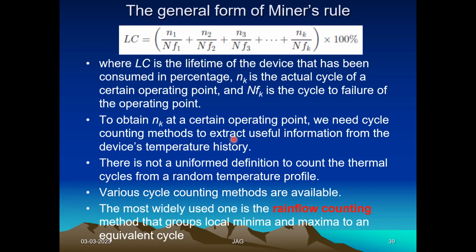How many climbings are there? What will be the length of each climbing, height of each climbing, for how long it will experience that climbing? So road profiles are published. Nationwide, it is published. If you Google it, you can see the road profile. So using the road profiles only, the design engineer can decide whether this particular component will work for me in my electric vehicle if it is running in this terrain.